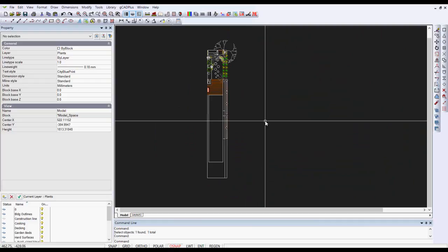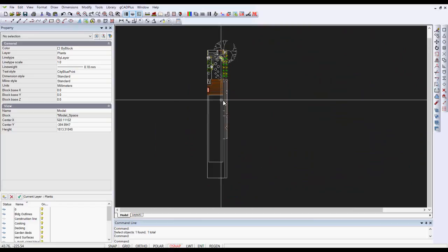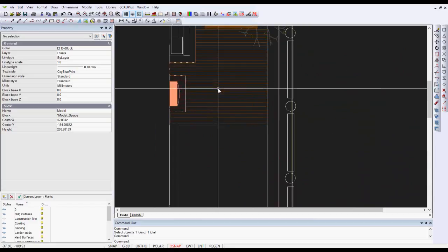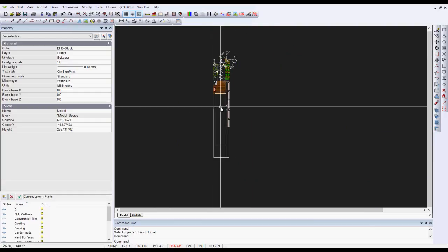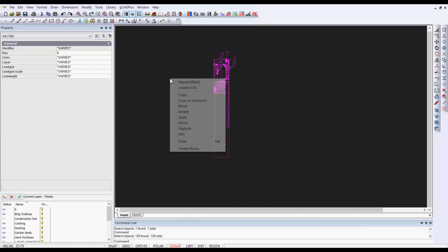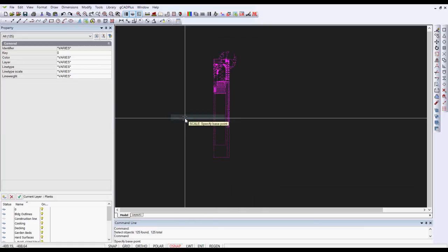You can probably scale up if you're using standard AutoCAD hatch patterns, but this particular drafter has used some seriously non-standard ones. So I think I've removed all of those, and what I'm now going to do is to select everything in the drawing and choose the scale option.